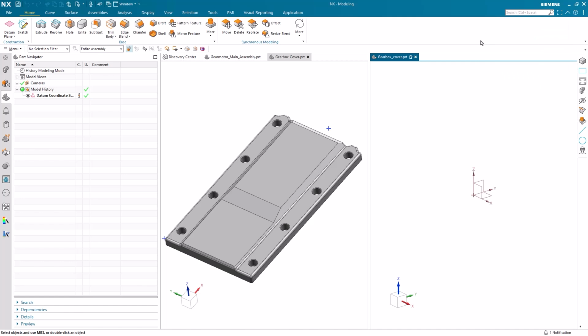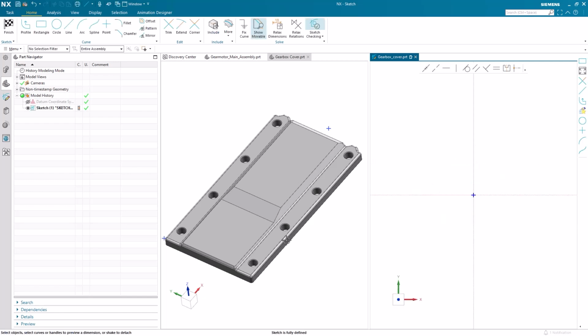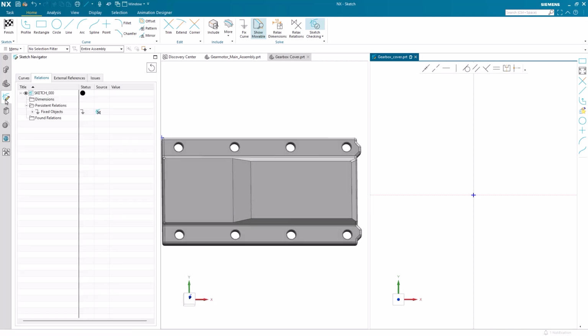our part. The first step in creating a new part is to begin with a sketch. The sketch command can be found under the construction group within the Home tab. Upon selecting this command, we are prompted to select the plane our sketch will be made on. When we're starting off, this isn't very important, but this step does become significant once other features have been created.